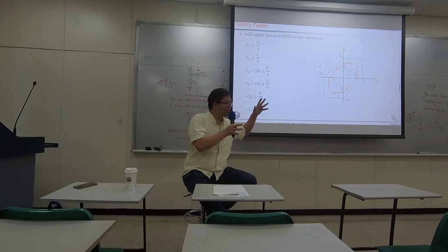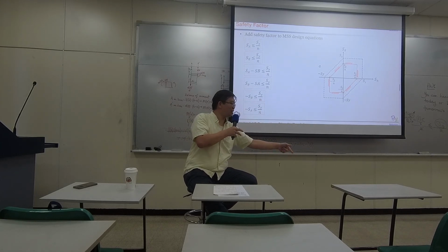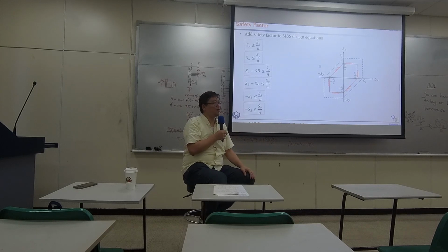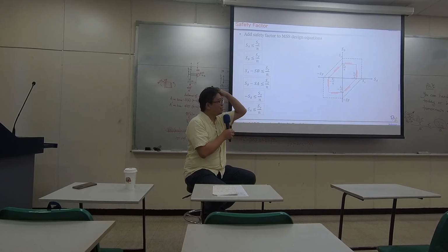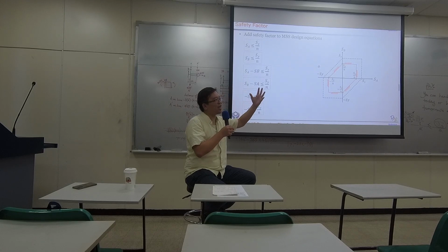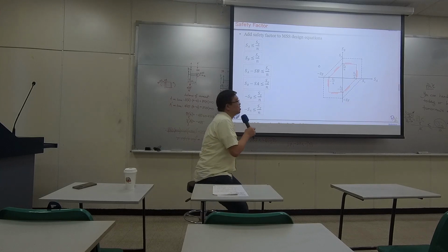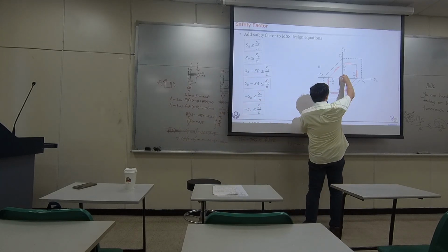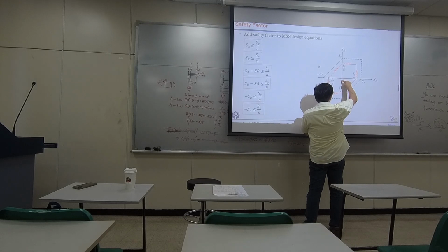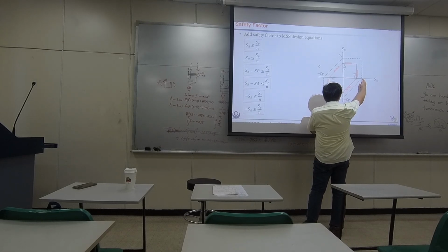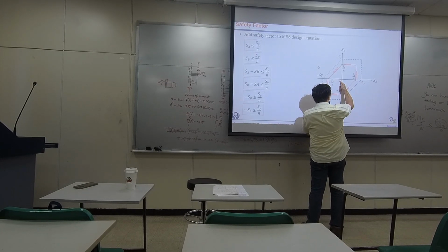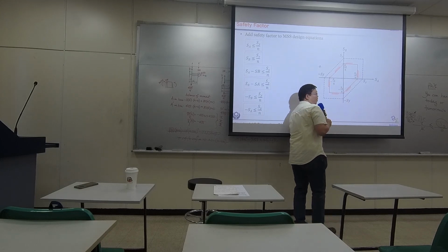Maybe that was the moment it's about to yield, and you're stepping in, make it break, right? So usually a mechanical design that is related to human life has such a large safety factor. It could be up to 10. That means we are only having our design within such a small area, because you divide this value by 10. So your safe region is so small right here for elevators.